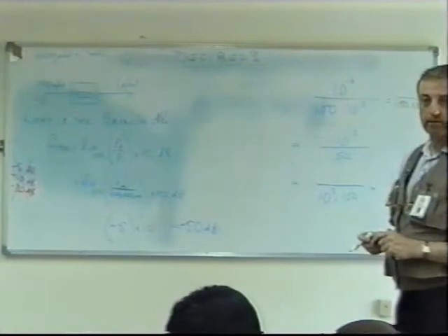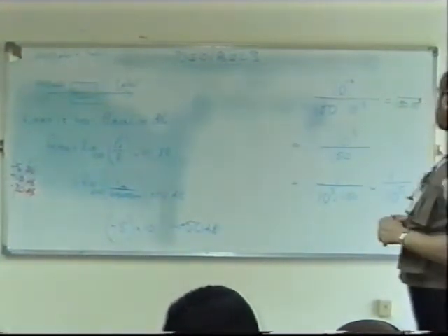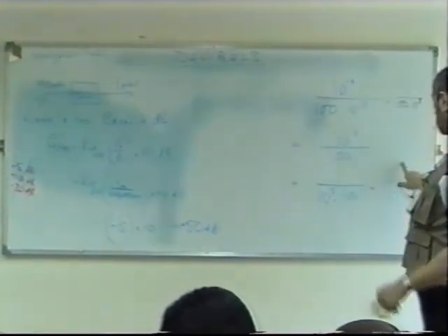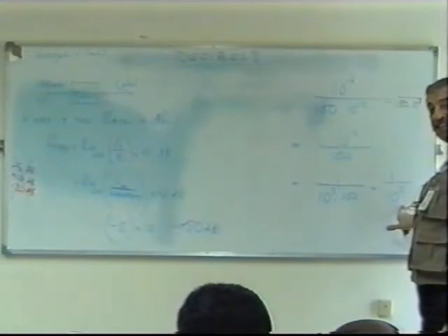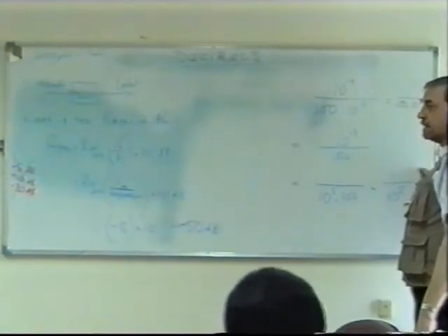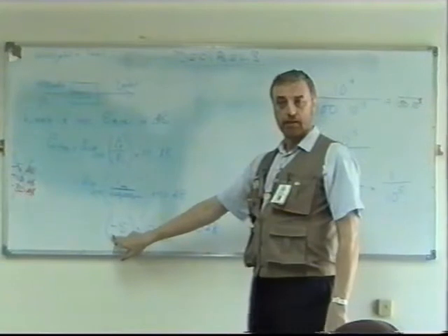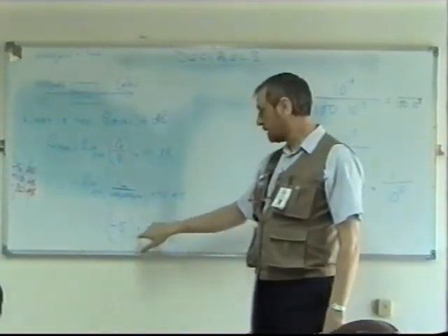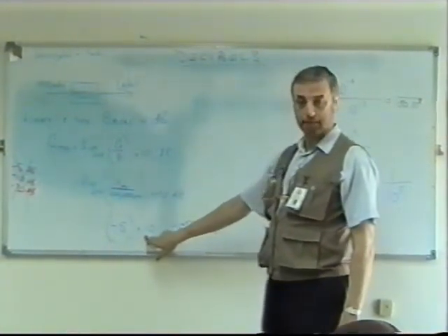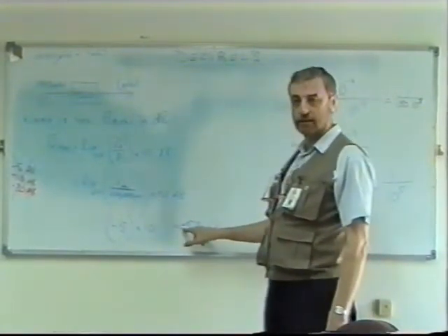It's the same thing. It ends up to be the same. So it's 1 over 10 to the power 5. Now 1 over 10 to the power 5 is 10 to the minus 5, isn't it? It's that indice we want. That's the answer to our logarithm. Minus 5. So that would be minus 5 bels, multiplied by 10 to bring it to decibels, minus 50. Don't forget the minus. It's very important.